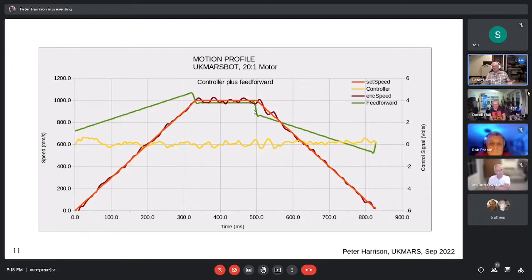And when it comes to brake, the same thing, right? You have to, it's a poor phraseology, but for lack of a better term, you have to suck current out of the motor, right? You have to have current going in the opposite direction to brake the motor. But nonetheless, it's current. It's accelerating current, decelerating current. So the step is negative and carries on down below 0. Because just before we come to a halt, we're actually trying to get torque in the opposite direction. So the size of this step is determining the amount of accelerating torque that goes in.